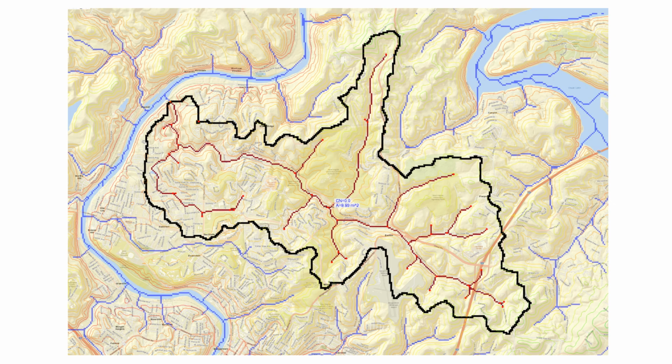Here's the watershed that we're looking at today. It's about 9 square miles in Morgantown. What I'd like you to do is identify the outlet. You can tell sort of from the shape of the river and the location of the interstate. I think you'll be able to define the project bounds using that shape recognition. And then delineate the watershed.